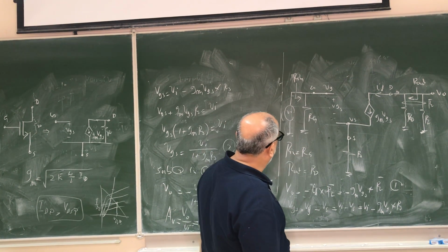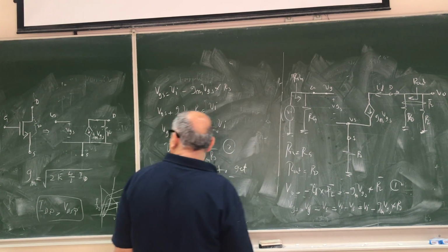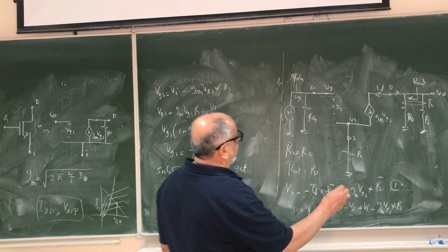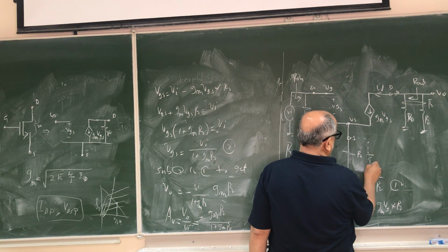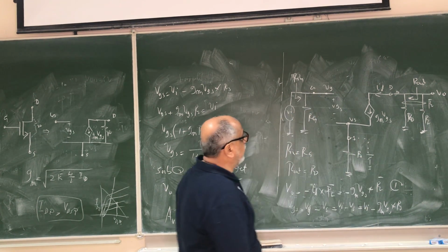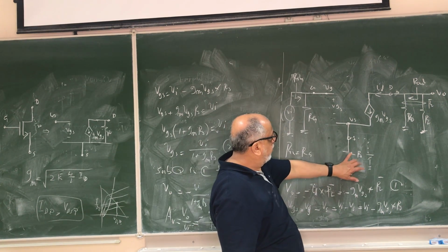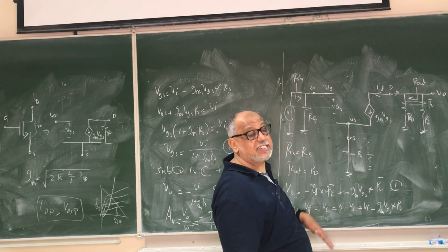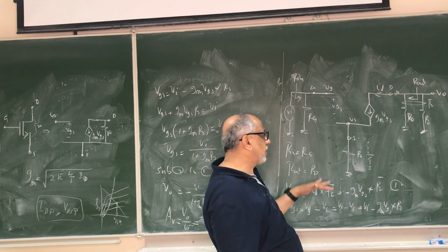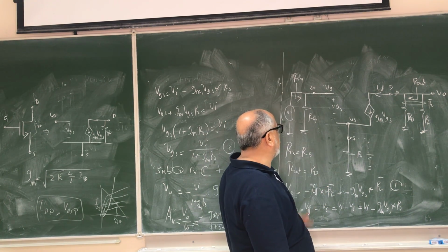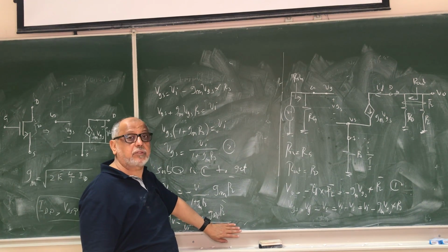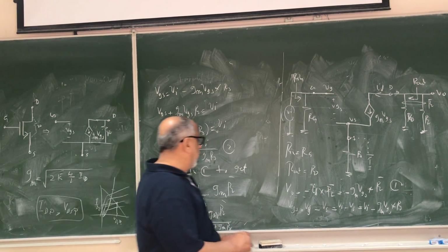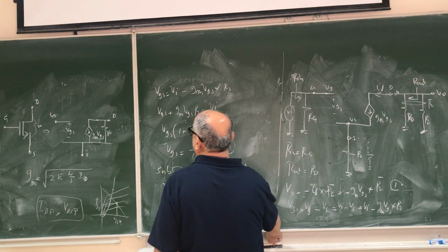So this is for the common emitter amplifier with RS. Now, if I want to increase the gain and just stabilize the bias point, then you can simply add a capacitor here. The bypass capacitor will short RS in AC analysis. It will keep it in DC, but in AC analysis it will short it out, and we'll have the gain the same as the previous one. Okay, so that is for the common emitter amplifier.